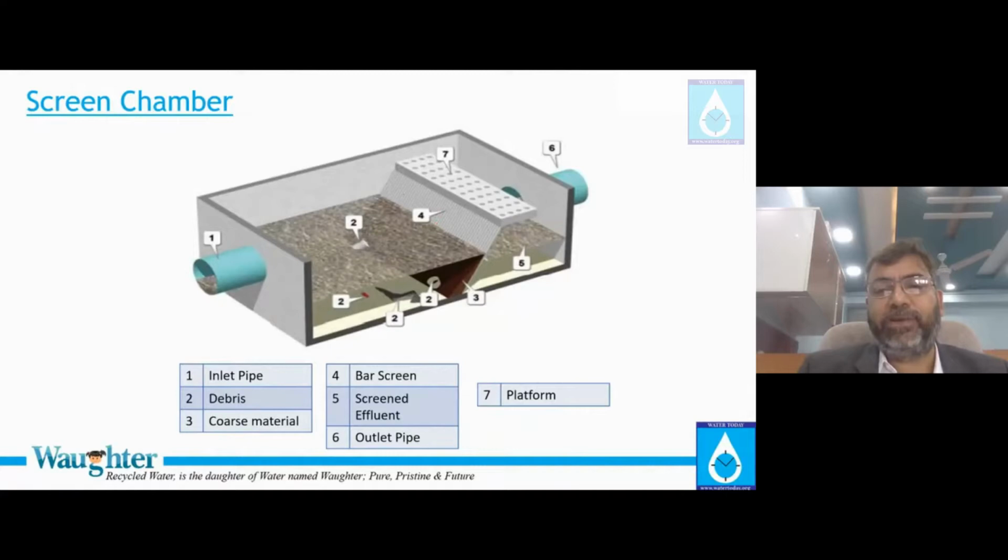So as far as this screen is concerned, I'm just driving this area. This screen, the water goes out. You can see the difference in level, right? Slight difference in level in these two. And this is the head loss of the screen, okay?